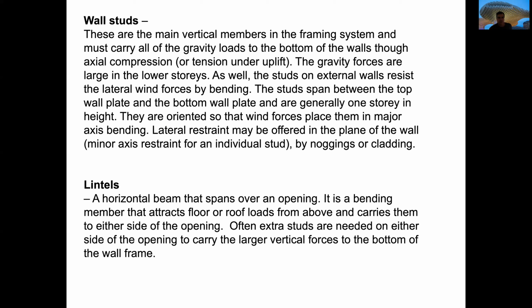The stud span between the top wall plates and the bottom plate is normally one story. However, there are some systems, like the balloon framing system, that allow two floor heights. They are oriented so that the wind forces place them in major axial bending. Well, the thickest area of that element will be perpendicular to the wind.